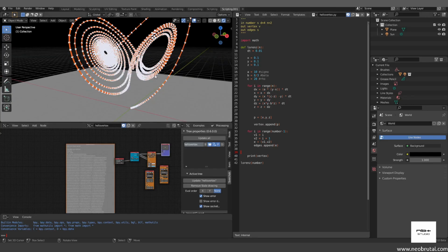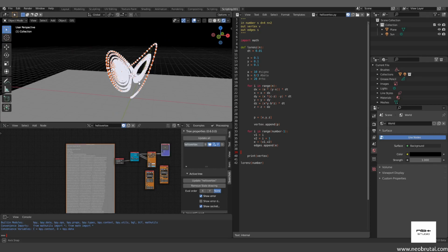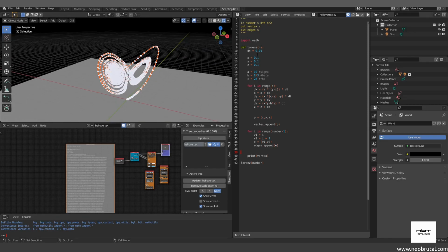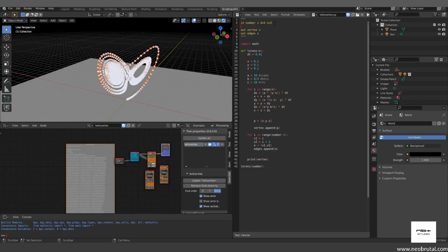What we're gonna do before we start working on the material and making a render out of this is we're going to actually add another parameter. So right now the only parameter is driving how many times we're iterating here, but now I actually want to be able to change from my nodes the dt. So let's create that, n, and then dt as the equals, our default value is going to be 0.01, and the nestedness level is going to be also 2. So we create our input.